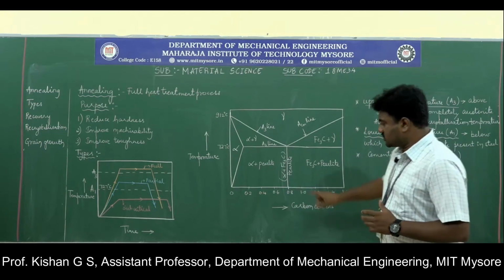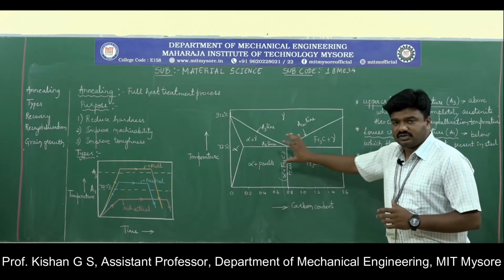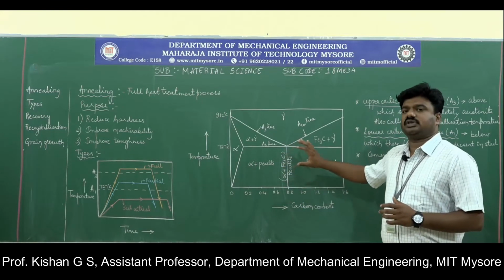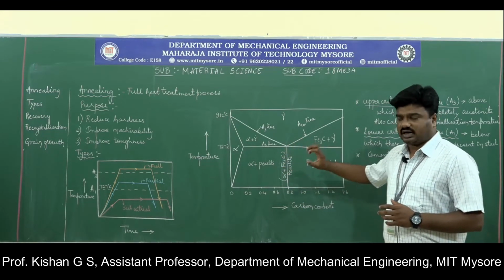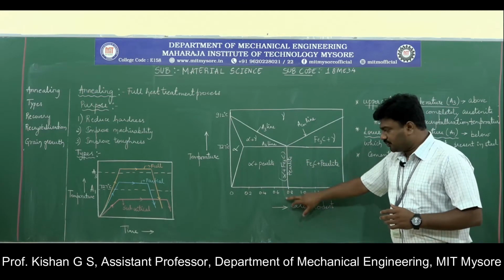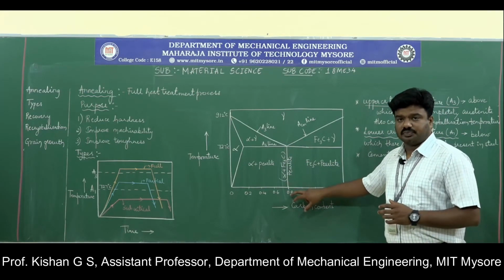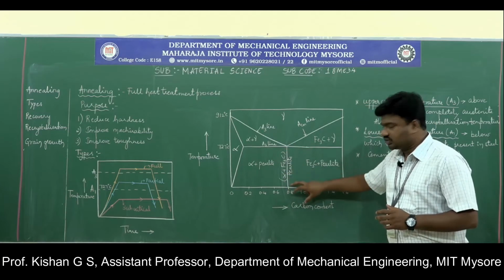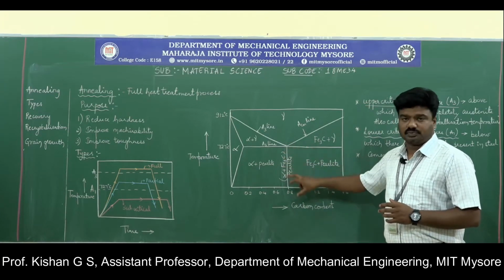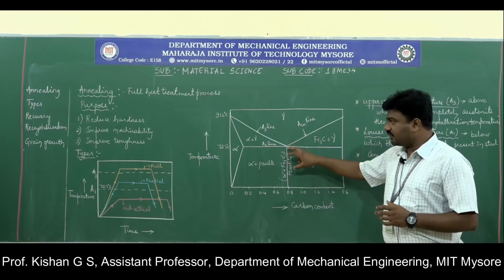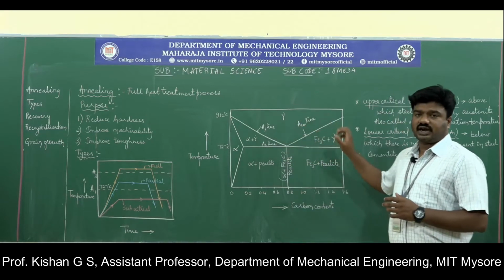Okay. In this eutectoid composition, observe the phase transformation here. This is only for the purpose of illustration or understanding. See here, along 0.8% or eutectoid composition, we have the composition of pearlite as the eutectoid composition, and with respect to that pearlite, we have different notations being identified.